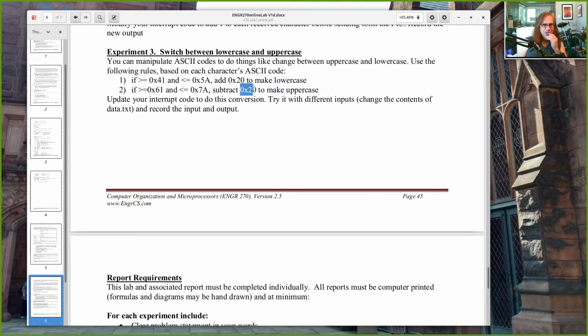USB communication is pretty complex, but there are a lot of devices, like a CH340, that will do translation between USB and serial. And they're a couple of bucks to buy. One end plugs into a USB port, and the other end has basically 3 lines: a transmit, a receive, and a ground. That's a really easy way to do serial communication through a modern computer, because our PCs don't have serial ports anymore, but those translate nicely.